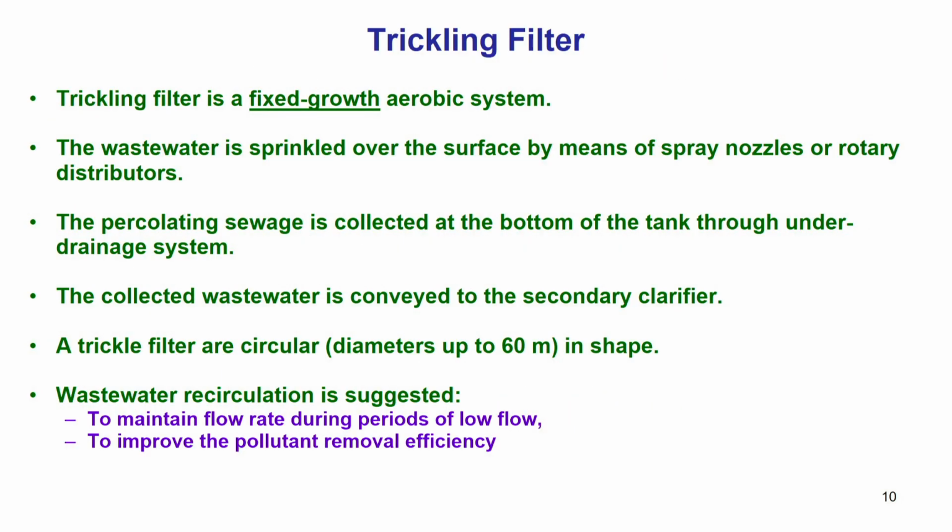Trickling filter is a fixed growth system. So we have to remember this thing. One question is, what is the difference between trickling filter and activated sludge process? Trickling filter is a fixed growth aerobic system.